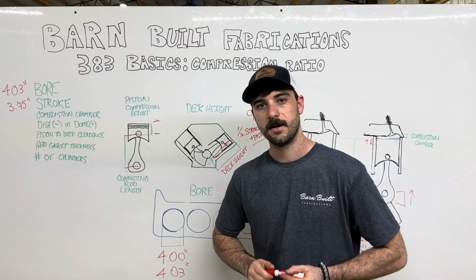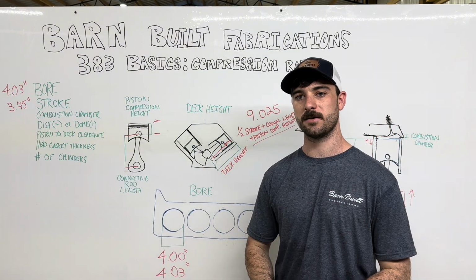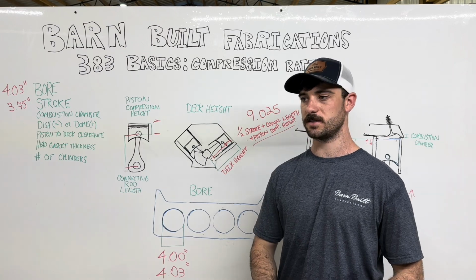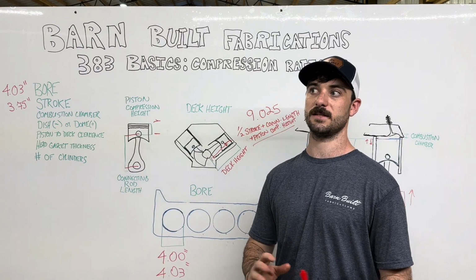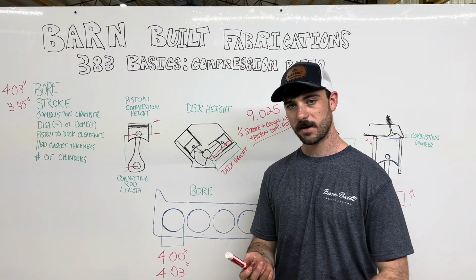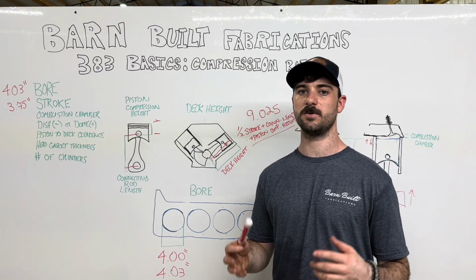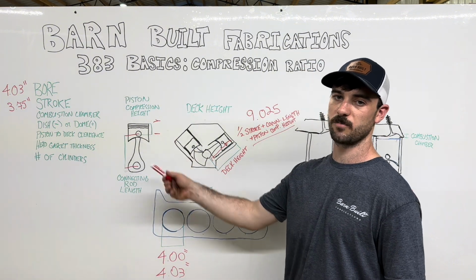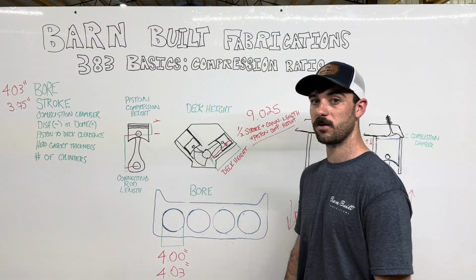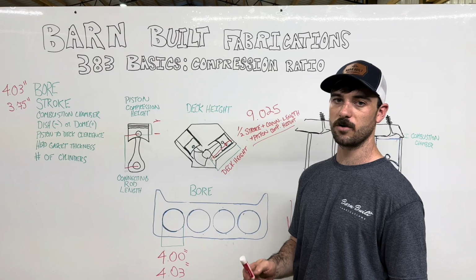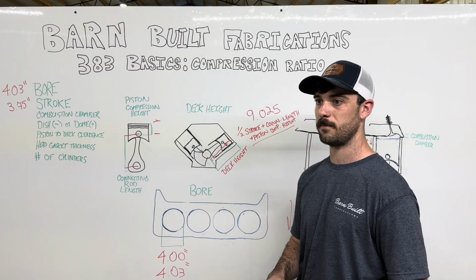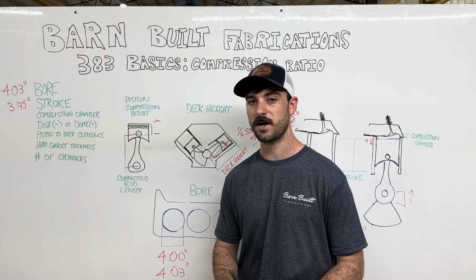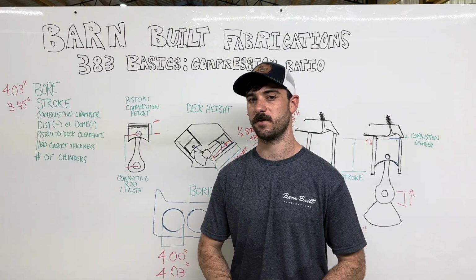But again, it brings us to another problem that I've been having, especially with part suppliers, and this isn't just one or two, this is a lot. Most piston manufacturers, or especially when you're looking at a rotating assembly specifically, they don't tell you what the piston compression height is. I'm sure you could probably call the manufacturer, but whenever you're looking at a rotating assembly that might have parts from different manufacturers, it can be really frustrating trying to figure that out.